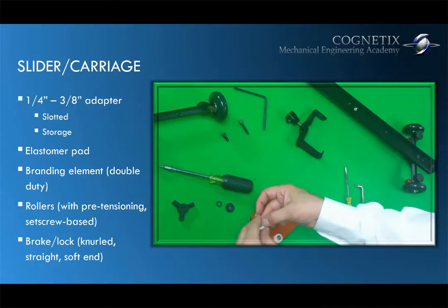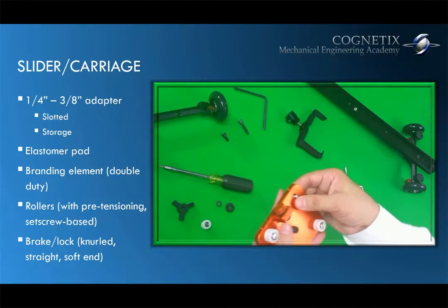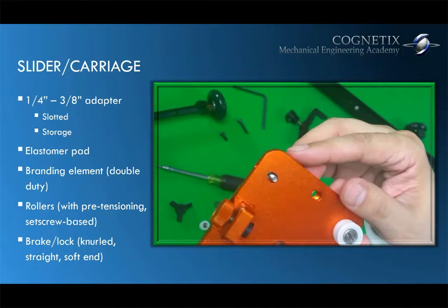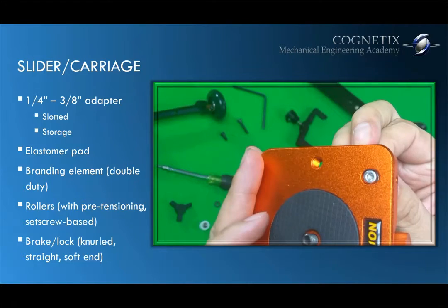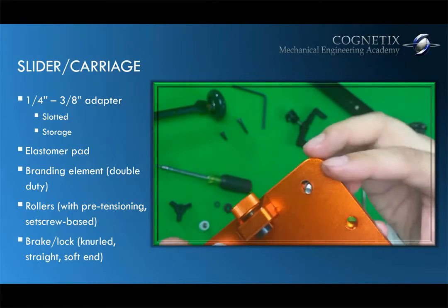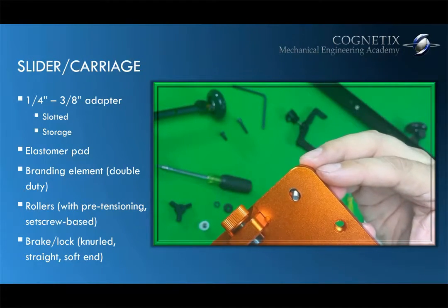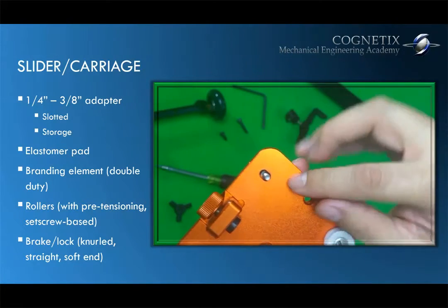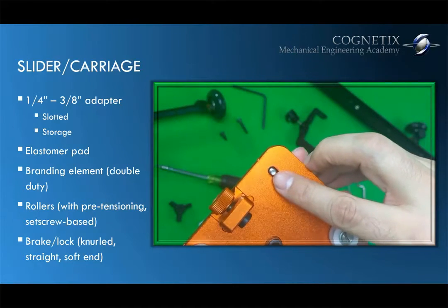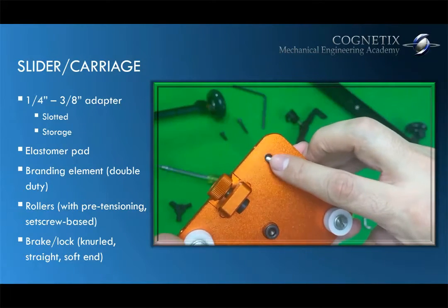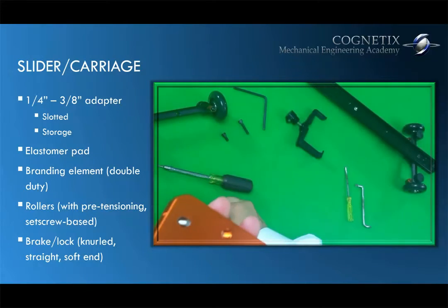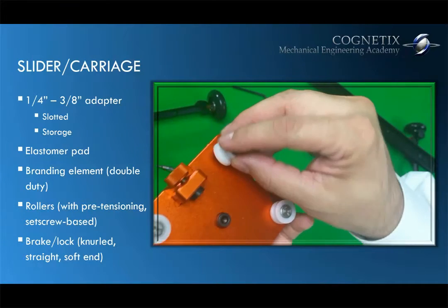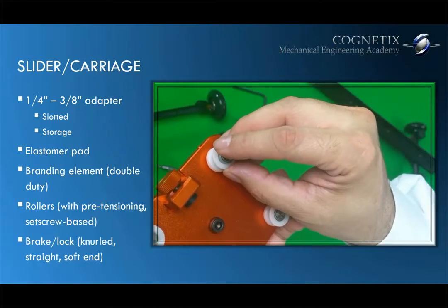Okay, now on the other end, we were talking about adjustability of the axis. So you can see from this end, we have a slotted hole, this end as well. So the axis of the screw can move out and in. We have it all the way in, and we have it all the way out. Okay? So you can imagine how this whole thing works: you have an axis there, you have an internal thread here, you thread that in there, and the whole roller is secured.